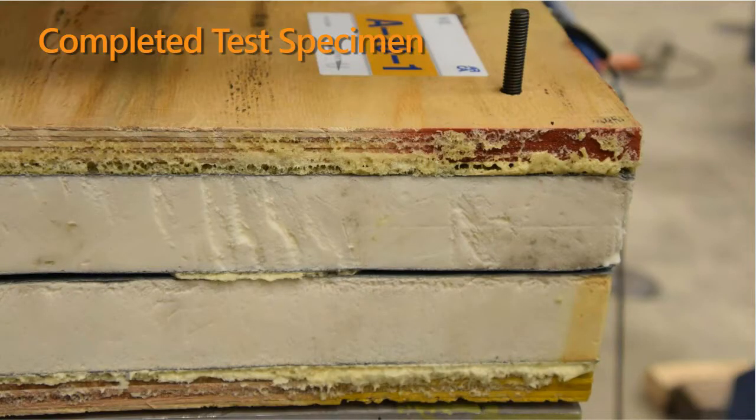So in this slide here, we have a completed test specimen. So here you see the ribbon of adhesive, got a nice spread on it, and that's due to placing the buckets on top of the samples that allowed the material to, for lack of a better term, smush itself and get wide adhesion there. And then up in the upper right-hand corner, we have our 3/8 inch metal studs that were screwed into the T-nuts that were installed prior to installation of the insulation board onto the plywood.